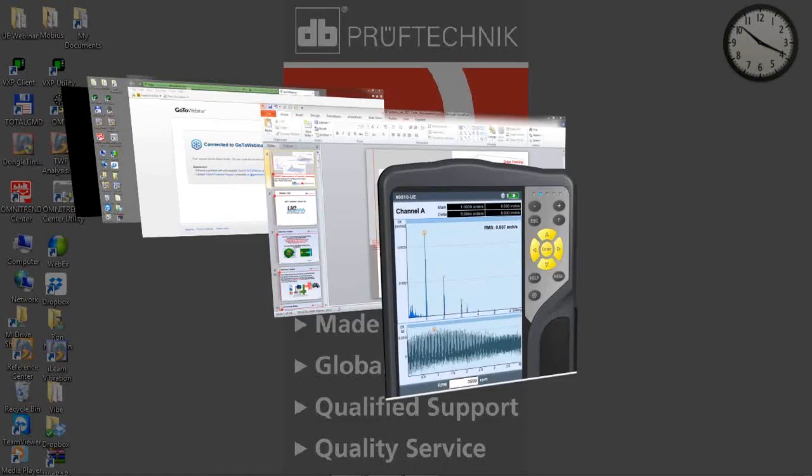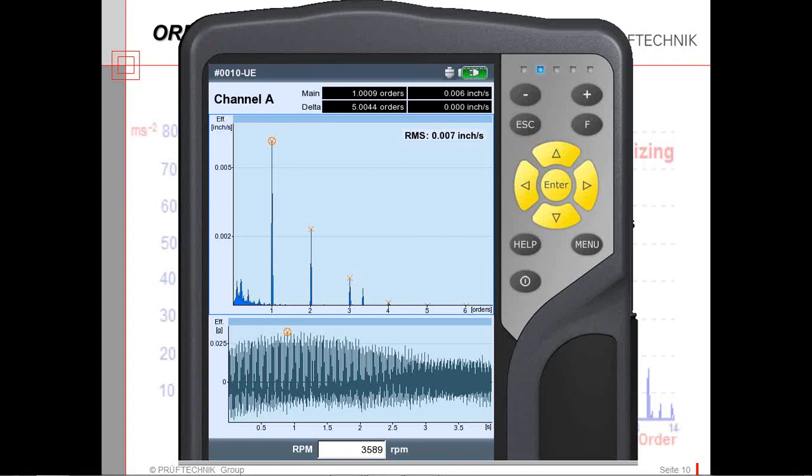So once again, if we go back to our spectrum here, we have mostly synchronous components in this little spectrum. So we have a 1x, we have a 2x component here, a 3x, and a 4x, and yet here's a small little component that's not 3x and not 4x. It looks like it might be about 3.4x. Now, this looks very suspicious. It may be a bearing frequency. And then we have some subsynchronous vibration here as well.